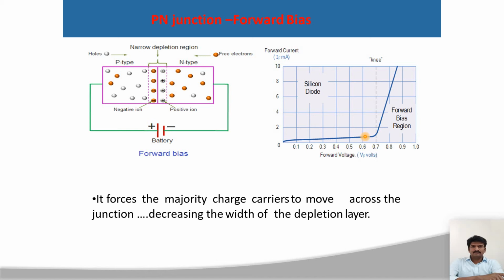Okay, thereafter, once it crosses the minimum voltage, that is the knee voltage, which you can also call the threshold voltage, the diode will start conducting. So the current passing through the diode will increase. Even after some time, if you keep increasing the voltage, the diode conduction current is not going to increase, because the free electrons of the given material are constant. After applying the maximum voltage, we cannot have an increment of the current. The same amount of current is there.